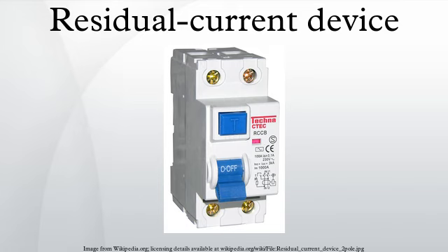For reasons of space, many devices, especially in DIN rail format, use flying leads rather than screw terminals, especially for the neutral input and FE connections. Additionally, because of the small form factor, the output cables of some models are used to form the primary winding of the RCD part, and the outgoing circuit cables must be led through a specially dimensioned terminal tunnel with the current transformer part around it. This can lead to incorrect fail-trip results when testing with meter probes from the screw heads of the terminals, rather than from the final circuit wiring.